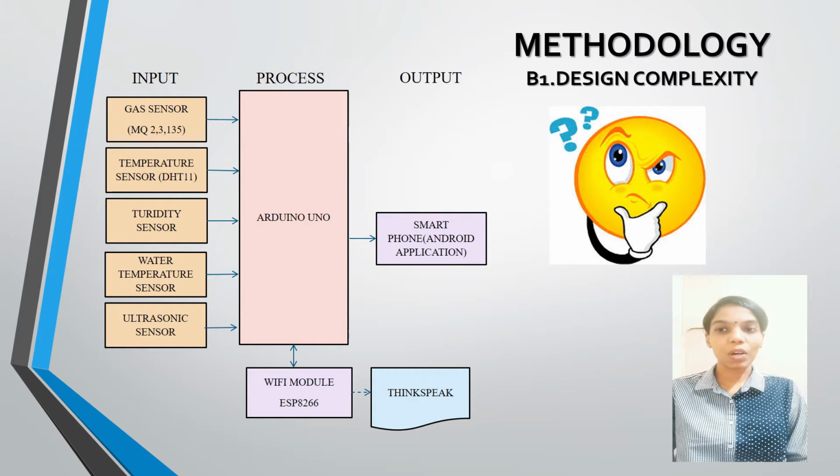Input data from all the sensors will be processed by Arduino, which produces output signals. The data will also be uploaded to ThingSpeak by using a Wi-Fi connection, ESP8266. This data is then sent to the Android app which we created before using MIT App Inventor, in order to display the output of the sensors in graph form to the users.